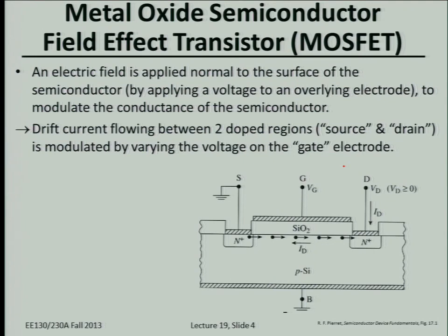That's a good question. What makes the electrons want to go from the left to the right? A transistor is usually a symmetric structure, in that you have heavily doped electron-rich N+ regions to the left and right. So you're right, current can actually flow in either direction. What determines the direction of electron flow is the voltage difference between the so-called source and drain regions.